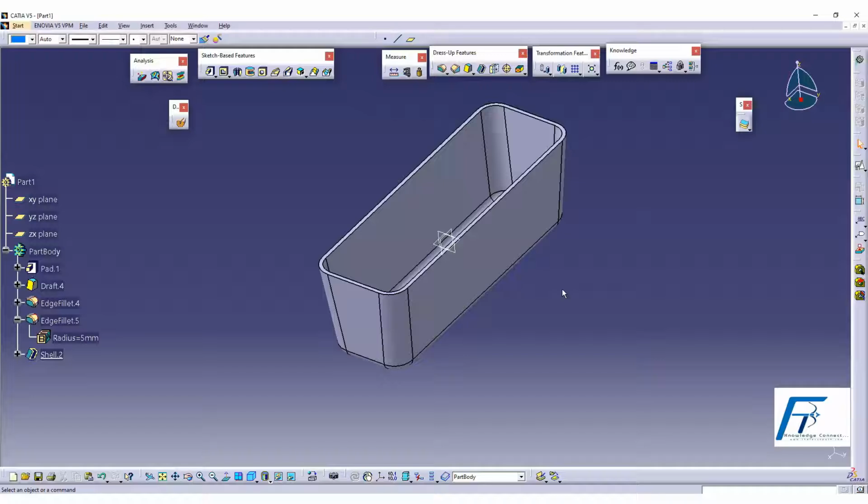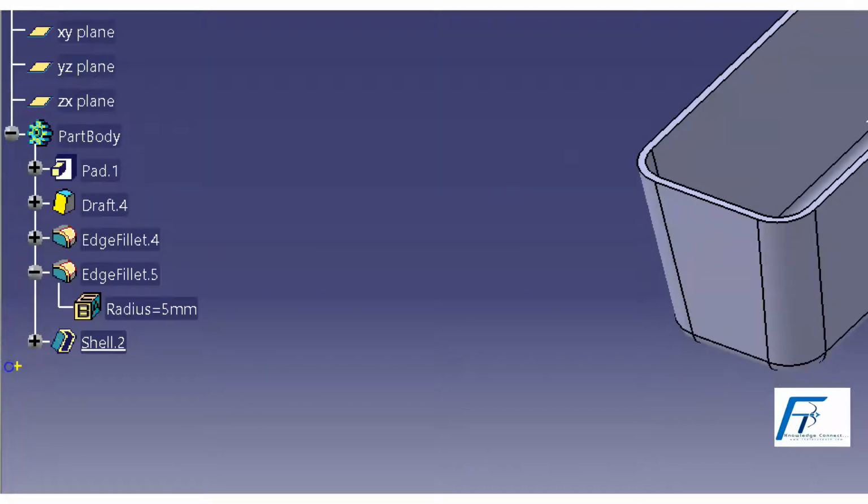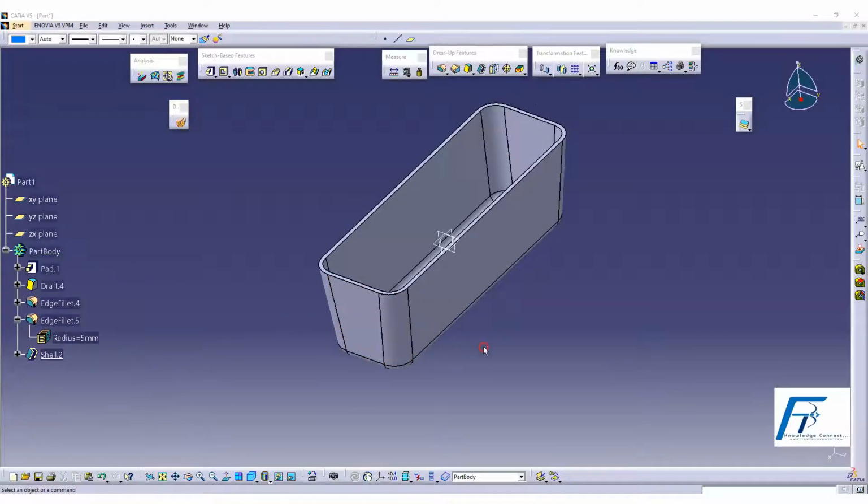Any fresher, when I interview, I give a tool test. The moment I see the specification tree, I will understand their integrity and knowledge of the design, right? I understand on what basis they will do it. They'll feel they have done a good job, but if they fail in the basic understanding of ordering the specification tree with the base features, the dress-up features, vertical edges, horizontal edges and shell, the entire design is not meeting the requirement. So that is the fundamental requirement which you need to understand. Okay? Are you guys there with me, please?